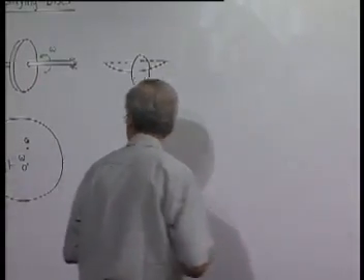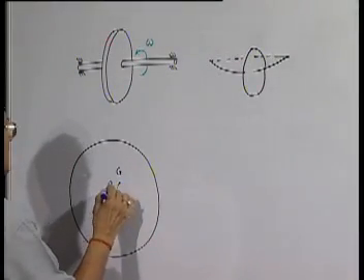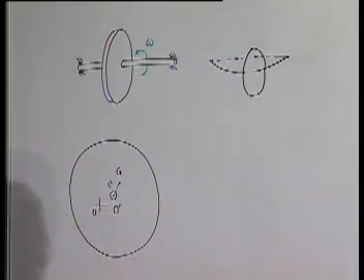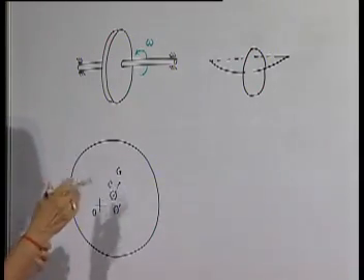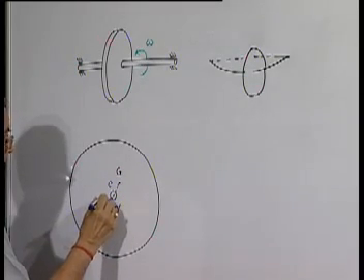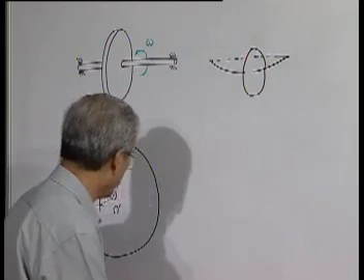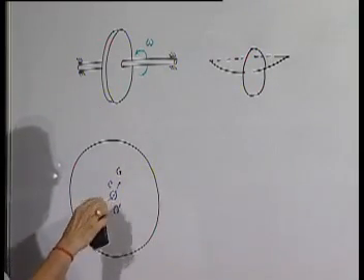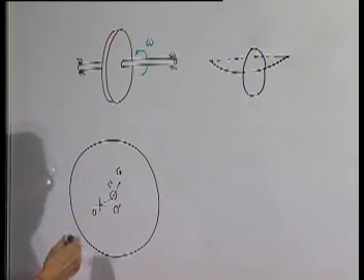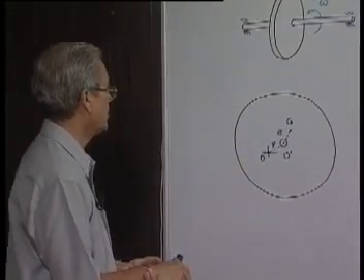That occurs very often, and let us see what we can do about it. So, if this distance is E, the eccentricity, which is inherently present because of wrong manufacture or fabrication, and this distance is R, or not R, because R may get confused with the frequency ratio, we can use rho. Rho represents the deflection of the shaft due to the unbalanced force produced.